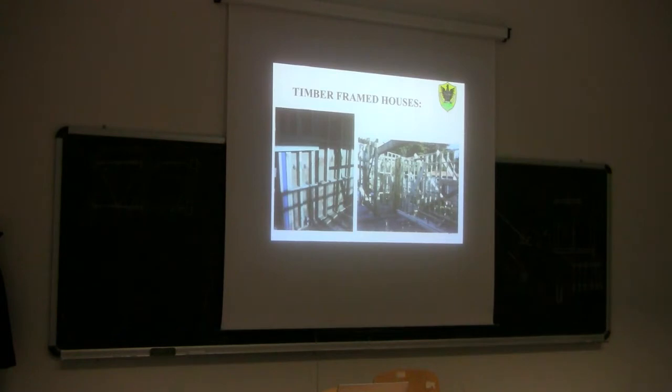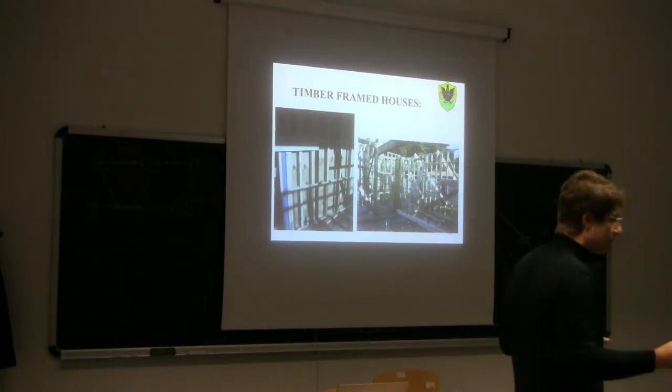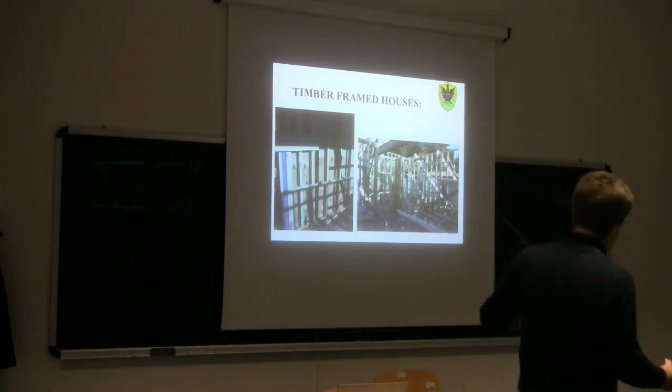Why do we need temporary bracing for this system here? Why do we need this temporary bracing when we construct the system? Because the system is unstable. We said before the bell frame is a non-stable system. So we need to place those temporary braces.